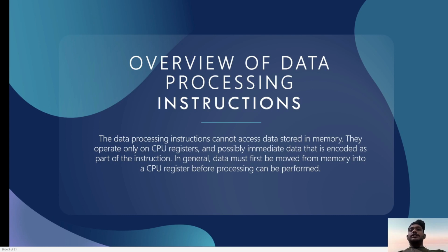The data processing instructions cannot access data stored in memory. They operate on CPU registers and possibly immediate data that is encoded as part of an instruction. In general, the data must first be moved from memory into a CPU register before processing can be performed.